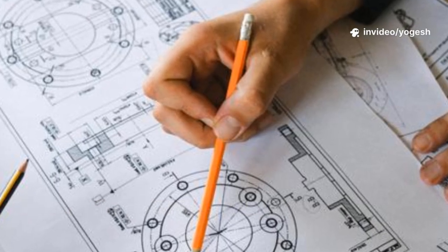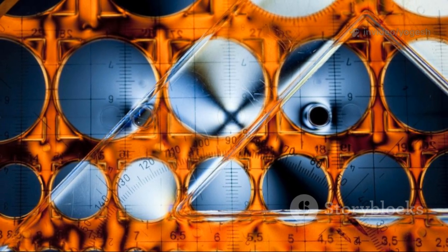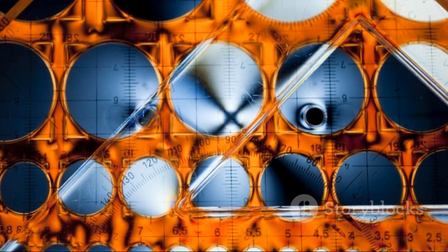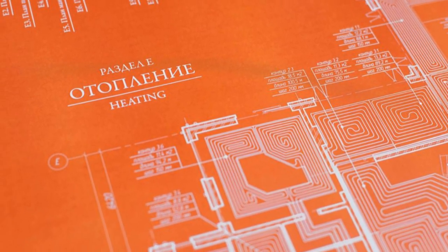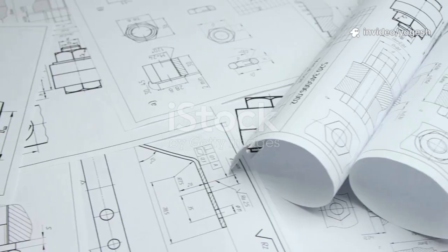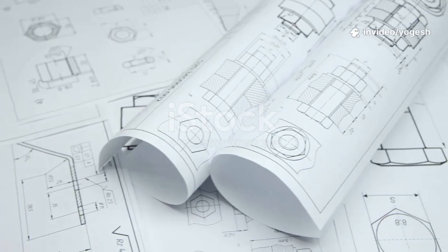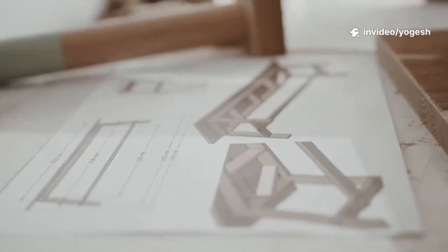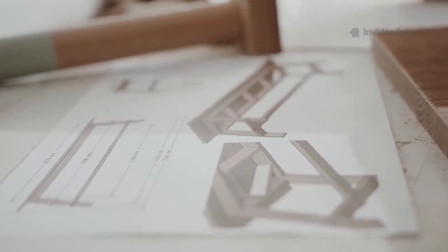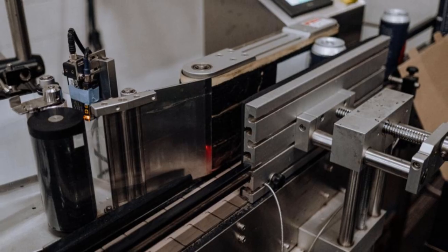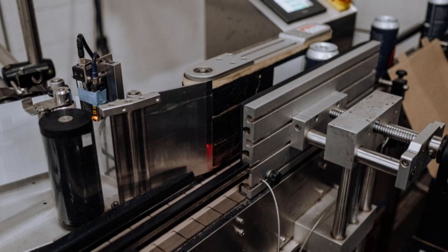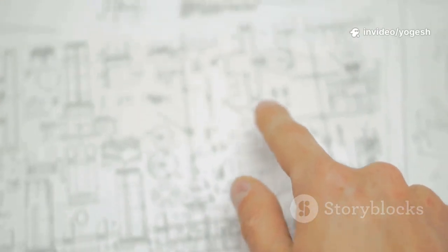Even with advanced CAD tools, drawing errors happen. Underdimensioning leaves features undefined. Overdimensioning causes confusion. Incorrect tolerances can make parts too costly or unusable. In assembly drawings, mistakes in the bill of materials, wrong part numbers, quantities, or missing items can halt production. Misplaced or missing balloons lead to assembly errors.